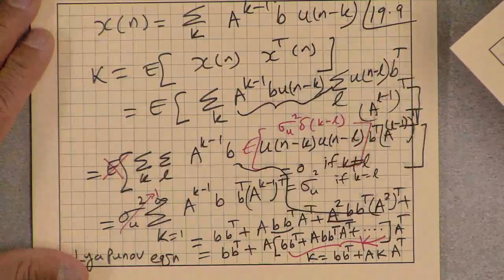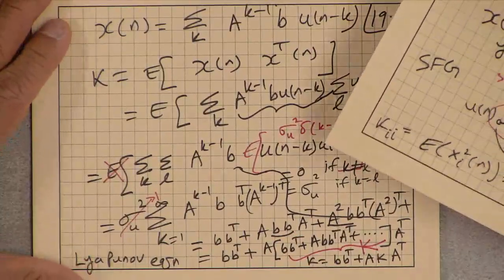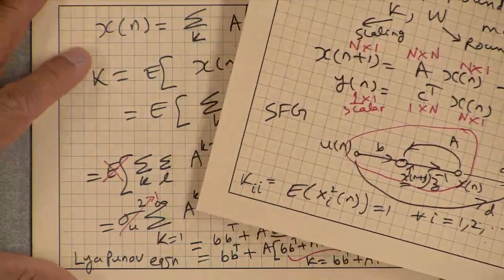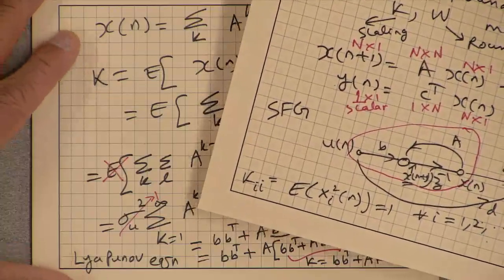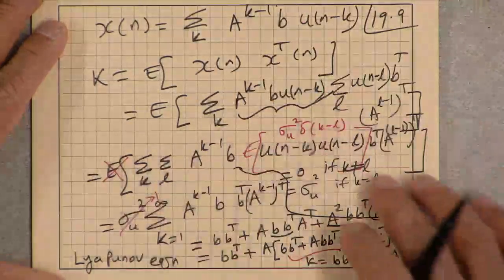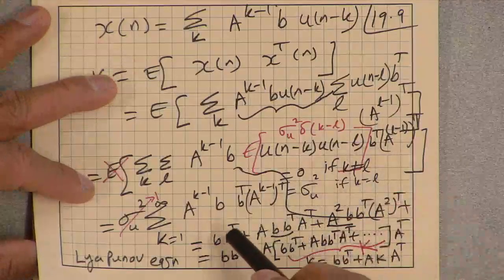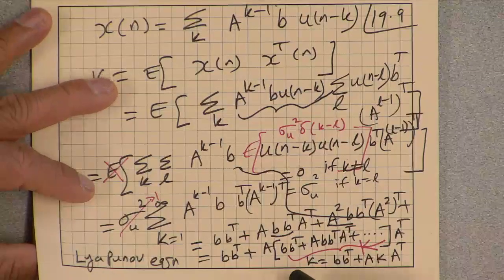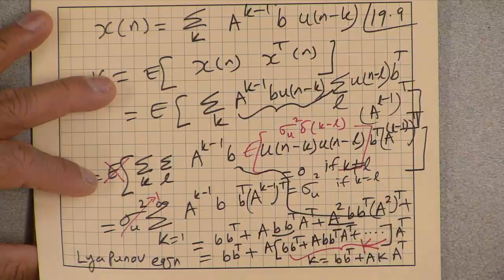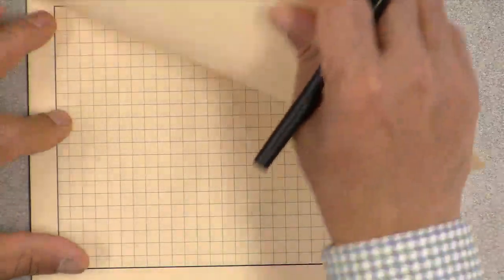That's the purpose of scaling: to scale the digital filter such that in the scaled state, the expected value of the scaled state squared will be 1. The reason we are computing all this K is that the K of the scaled matrix that we can compute from this original K will have 1 in all diagonal elements.